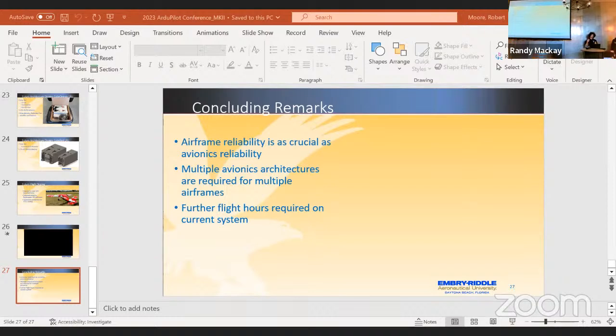I did a bit of limited and ground testing for Copter. The good news is that it does work as intended. In terms of what I'm doing with plane right now, I'm keeping it to the manual flight mode, just so nothing gets deflected. Buzz, you have a comment? I was just going to say, for plane, you might be able to use Lua to zero your integrators. Oh, maybe. I think the work Leonard's done on Copter really paves the way.